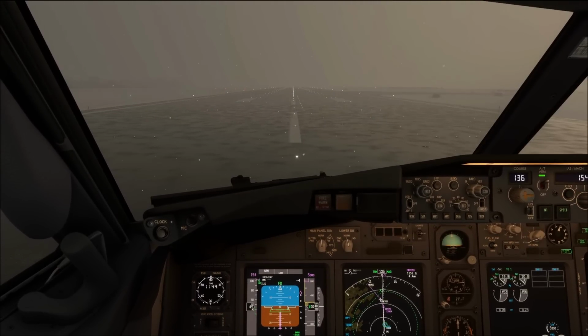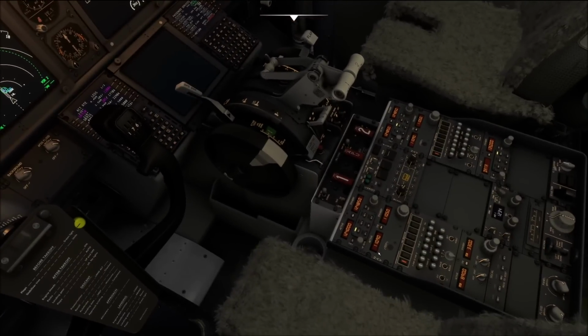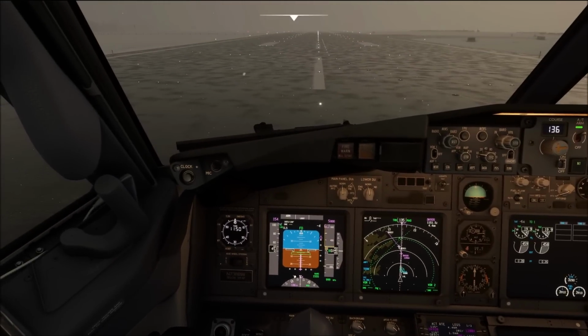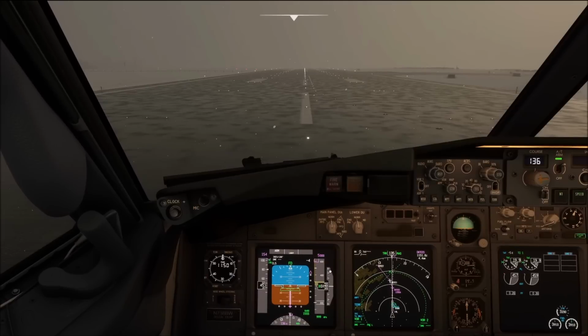Winter operations is often associated with low visibility conditions, and right now the visibility is alright, but it is varying slightly every now and then, so a quick reminder here: if you do encounter low visibility conditions, you need to tune the ILS frequency of the runway that you're on. In our case that is 110.9, and we do verify that we are exactly on the localizer up here. That is very important in case you have parallel runways where you might have lined up on an incorrect runway, like that accident with the 747 in Asia, where they lined up on a closed runway and ran into construction on the takeoff run. So be very careful when you are doing this.